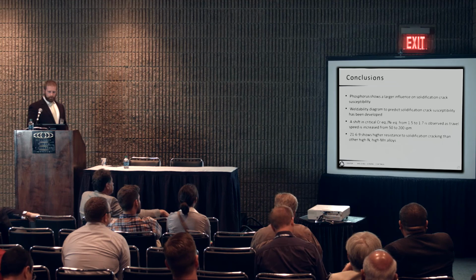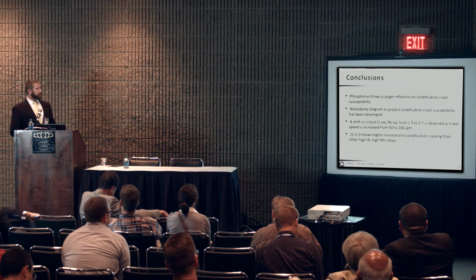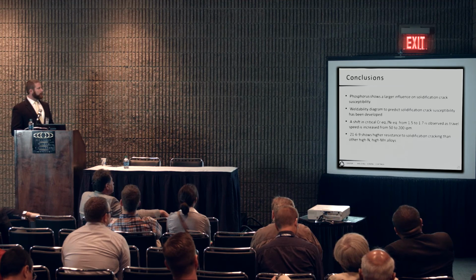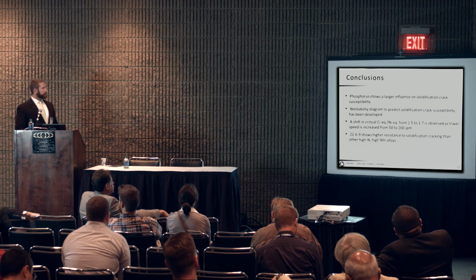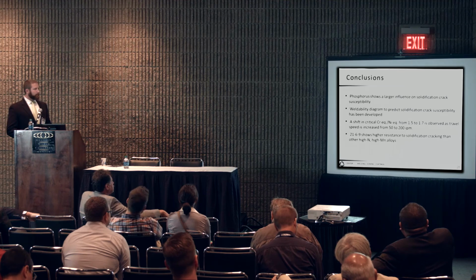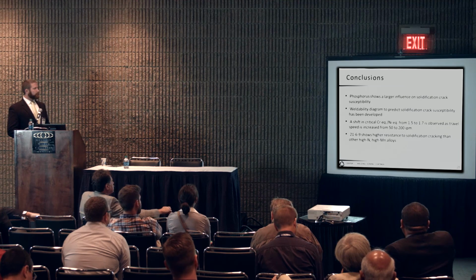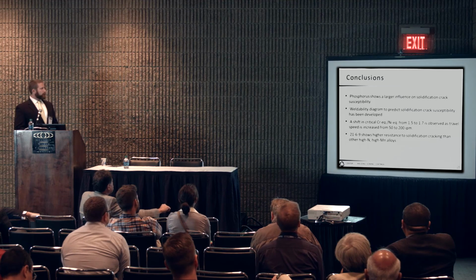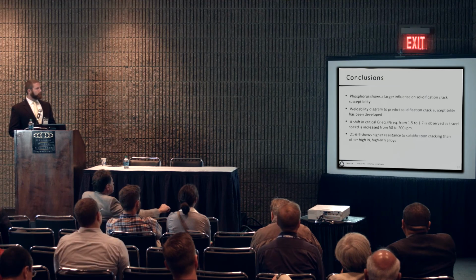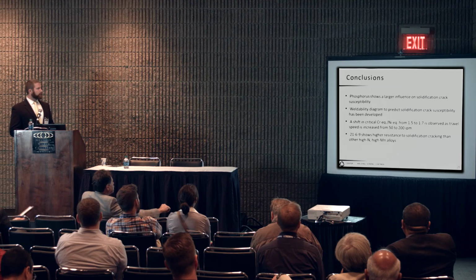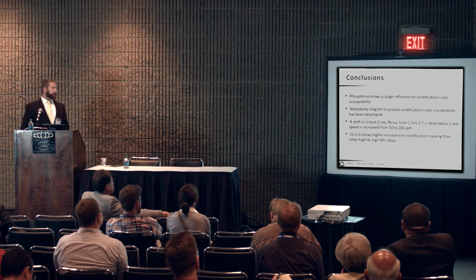And finally, conclusions. Again, phosphorus shows a larger influence on solidification crack susceptibility for the chemical compositions tested here. The weldability diagram to predict the crack susceptibility has been developed for laser welding at multiple travel speeds. We see a shift in critical chrome over nickel equivalent from 1.5 to about 1.7 as the travel speed ranges from 50 to 200 inches per minute. And 2169 shows higher resistance to solidification cracking than some of the other high nitrogen, high manganese alloys.